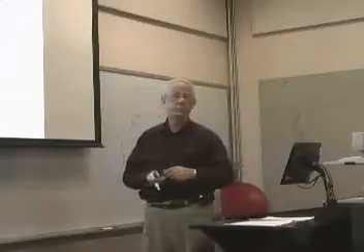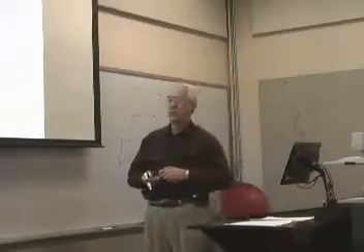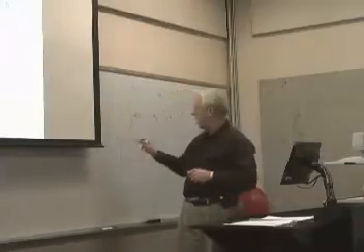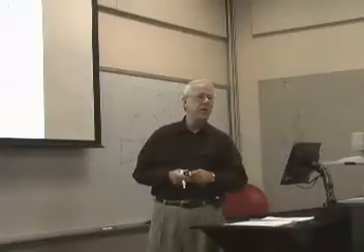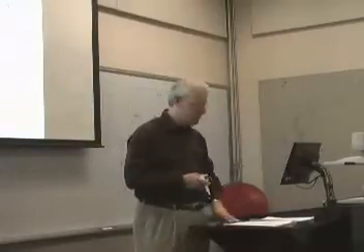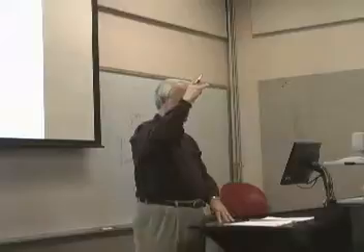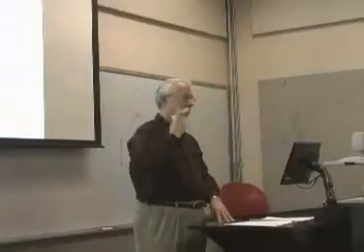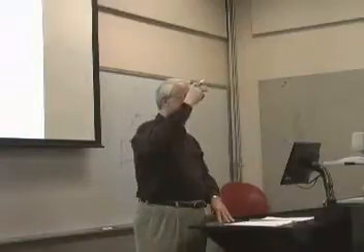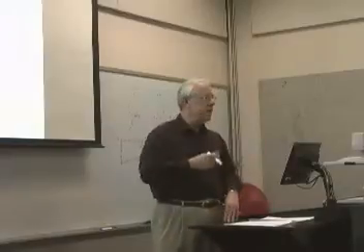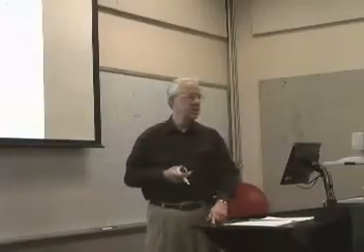That only works if the structure is uniform, correct? No. It does not have to be structured. It can be irregular. And in fact, with the boundary element method, you can have what are called infinite boundaries. So you have the surface of the Earth, and you want to model airflow through a certain region. What's the upper region going to be? 1,000 meters? 10,000 meters? Outer space? So with a boundary element approach, I can actually have an infinite boundary if I want.